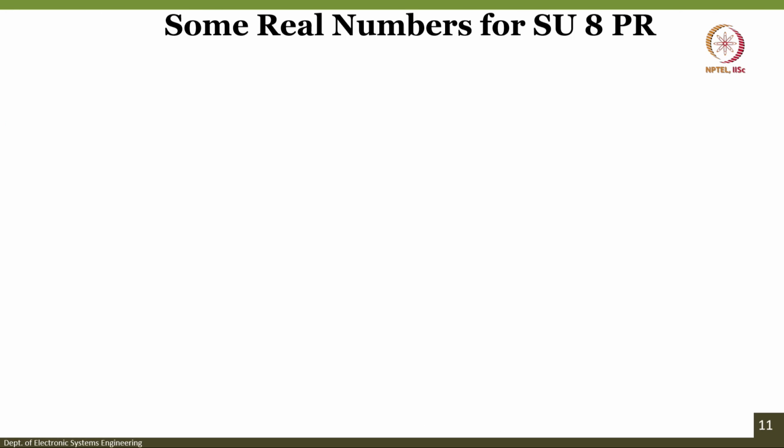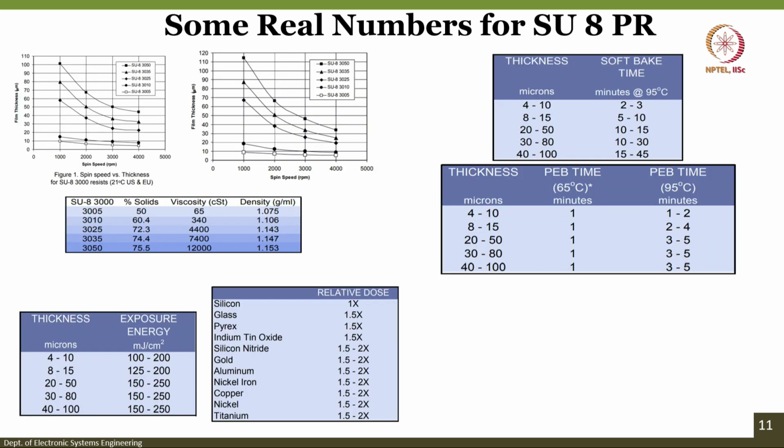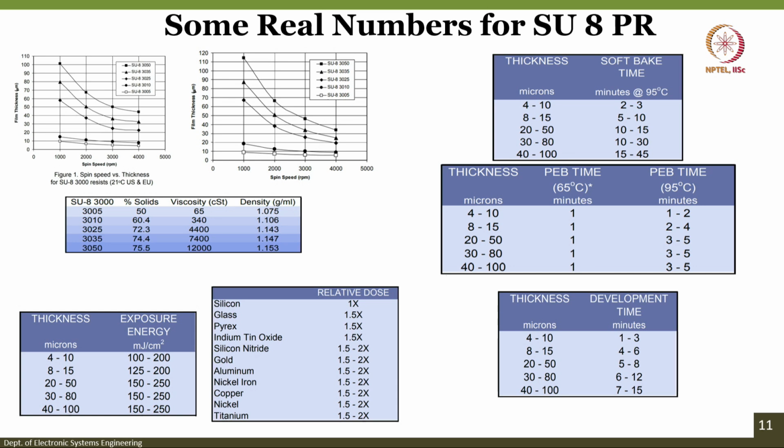This is a slightly quick point which I want to make, because all of you know what photolithography is. It is very important to know what the actual values are. So this is for SU8. SU8 is a negative photoresist, frequently used. You will never get a complete list of materials used to make an SU8 photoresist. That is something, a trade secret, which PR companies keep. They will give some name like AZ222, something like that. And for SU8 alone, there are 5 variants.